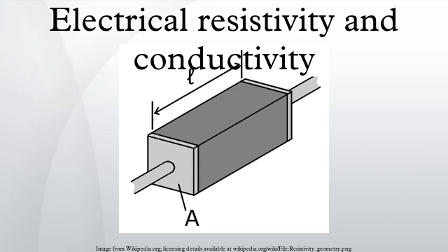Resistivity density products. In some applications where the weight of an item is very important, resistivity density products are more important than absolute low resistivity. It is often possible to make the conductor thicker to make up for a higher resistivity. And then a low resistivity density product material is desirable.